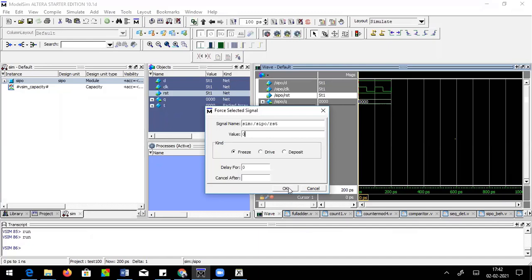It's always important that in a flip-flop, you don't know what the next state is unless you bring them to the known state. Because in a flip-flop or a connection of flip-flops, the next state depends upon the present state and the input again. If you are not aware of the previous state, then you can't determine the next state, right? So it's always better to bring counters or any sort of sequential network to the known state by making reset 0 and then go ahead for doing it.